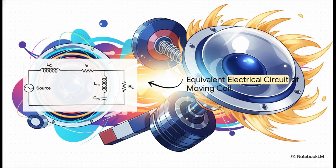Now, what's really interesting about this slide is how physical mechanics translate directly into an equivalent electrical circuit. It's honestly like a mathematical puzzle fitting together. L, C, and RC represent the basic electrical inductance and resistance of the voice coil. But if you look closely at the variables L, M, and Cm, the mechanical mass of the moving physical system is perfectly represented as electrical inductance, Lm, and the mechanical stiffness or compliance is represented as capacitance, Cm.